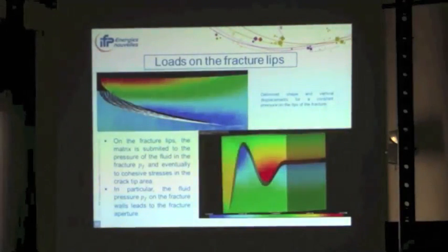So now the loads on the fracture lips. Here are some images of cracks submitted to constant fluid pressure. The important thing here is that we are able to catch the curvature of the crack with very few elements. And so you see the deformed shape. The fluid in the fracture opens the crack.